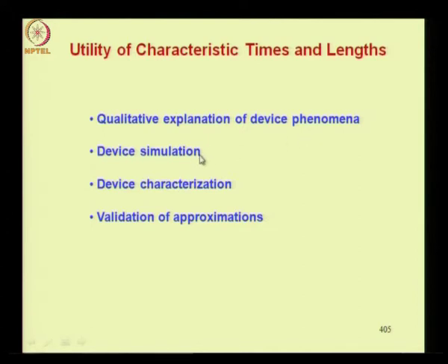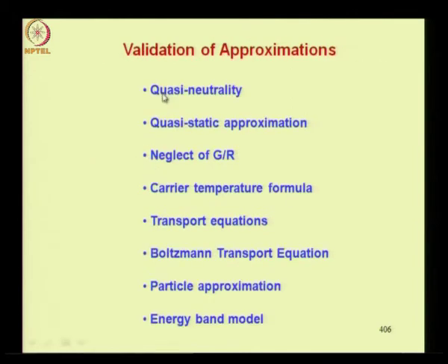For device simulation, we considered simulation of surface recombination by volume recombination, and for device characterization we considered measurement of the doping profile and showed how Debye length is coming in the type of doping profiles that can be characterized. Validation of approximations was done. This topic was discussed at great length, and we discussed all these approximations, their validations: quasi neutrality, quasi static approximation, neglect of generation or recombination, carrier temperature formula, transport equations, Boltzmann transport equation, particle approximation and energy band model.